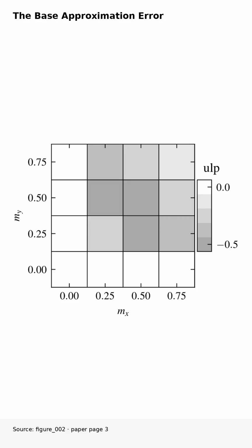Because this baseline error is always bounded and never exceeds half a ULP relative to the exact result, the system can exploit it. For modes like round to 0, the approximate result naturally falls into the correct mathematical bin. Consequently, these rounding modes can be obtained directly with zero hardware correction overhead, eliminating the need for extra carry-in logic.